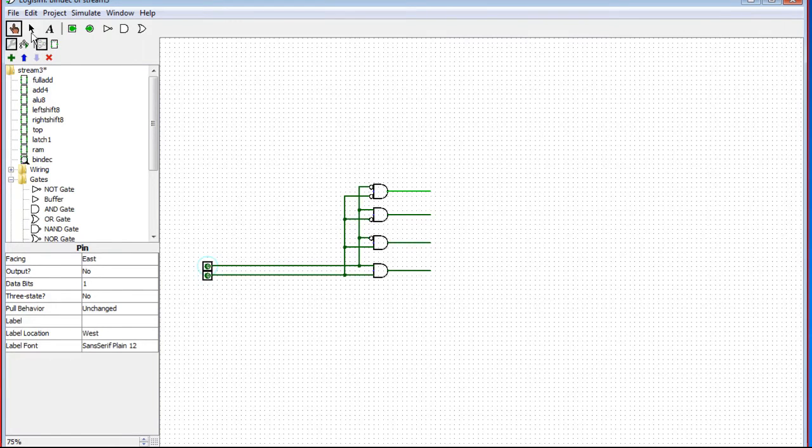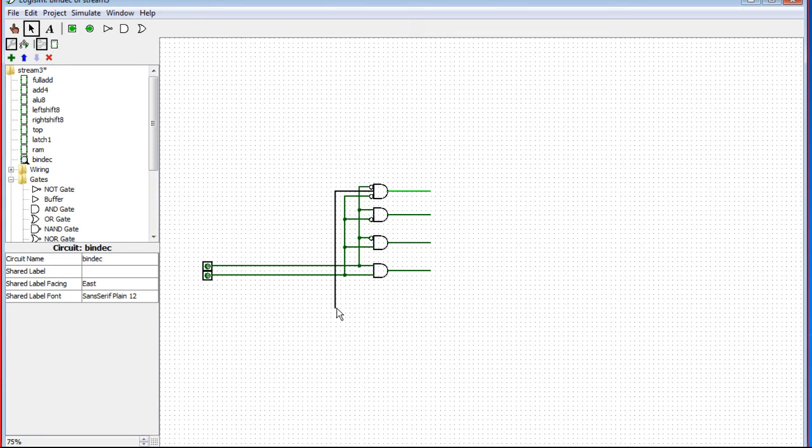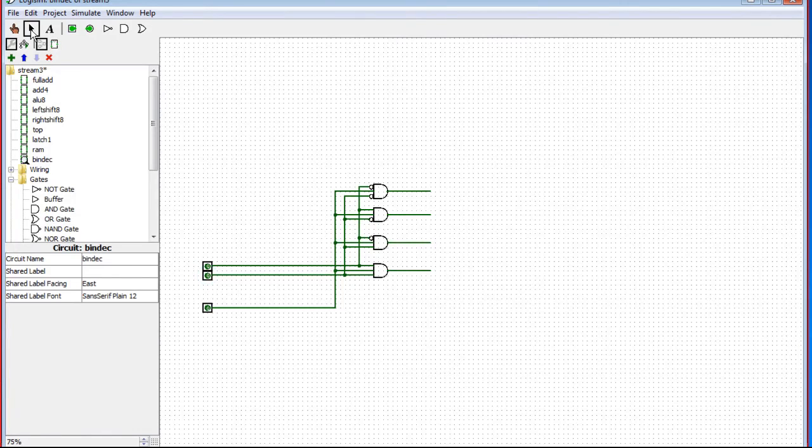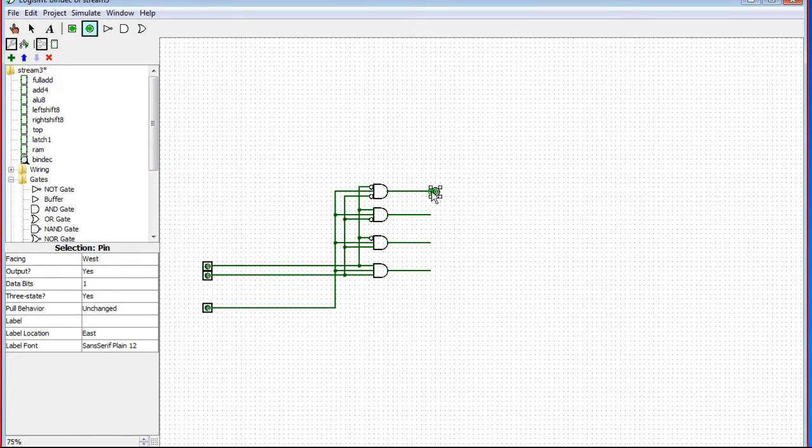Now what we do is we add in here a third line. We'll call this one the enable line. And I'll put that there. Good. And now if this is 0, doesn't matter what we get here. Output, nothing is output. And that is your basic 2-bit binary decoder.